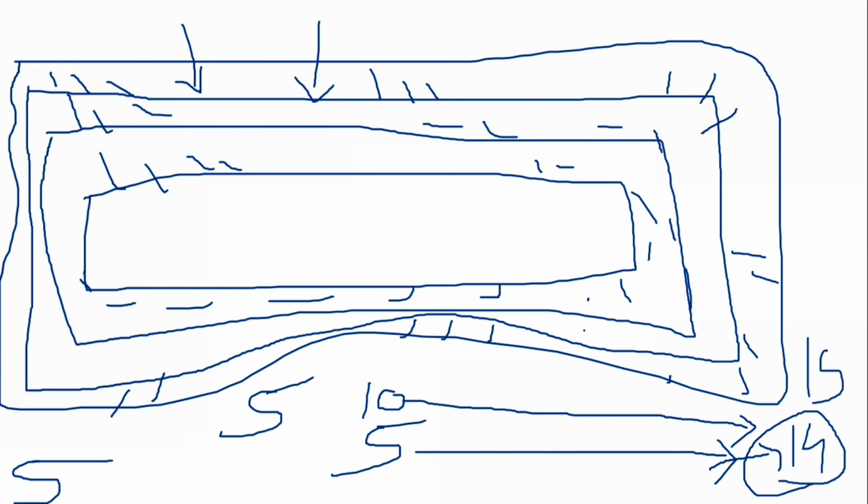It is lowered like this. After that, I change my stage. I come to the second stage. Again I install my Wellpoint system, then again I start my dewatering system, and again it looks like this. Again it is lowered by 5 meters.